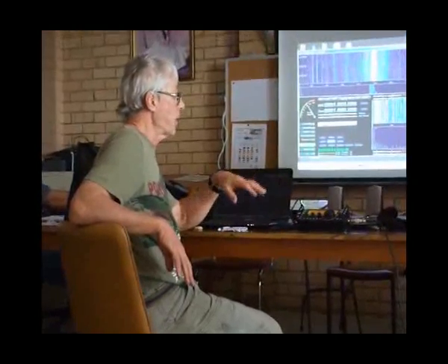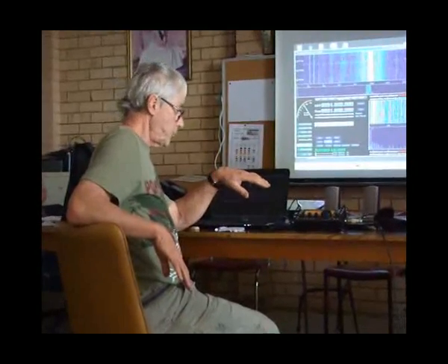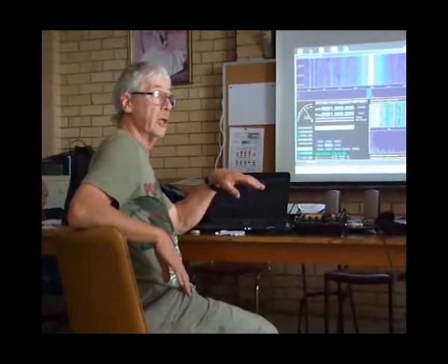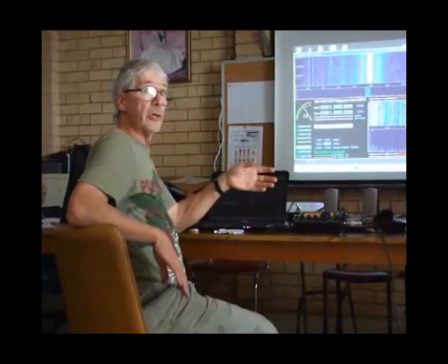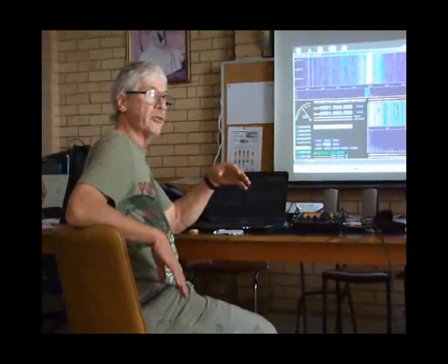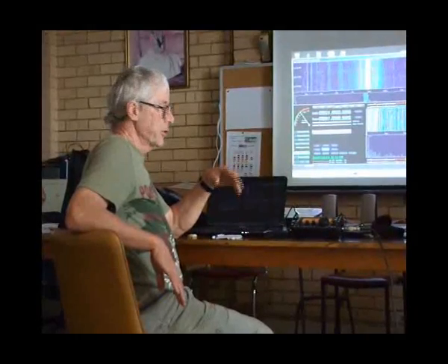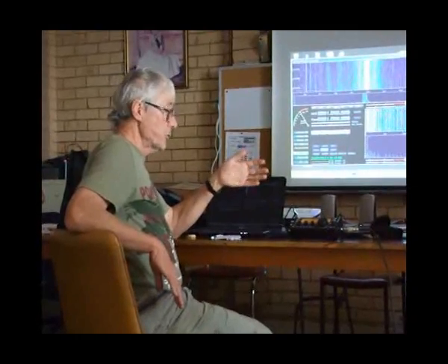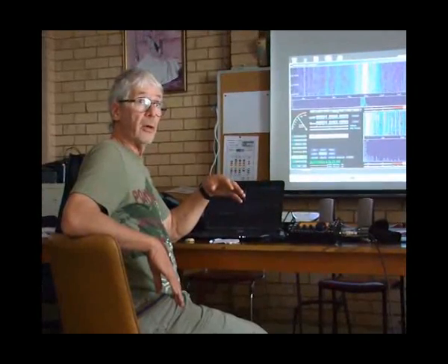It goes through bandpass filters and amplification, but then it goes through a system which turns the RF signal into this phase quadrature signal, or IQ, which is a two-channel signal, 90 degrees out of phase, and the digital signal processor is able to convert that to analog audio.